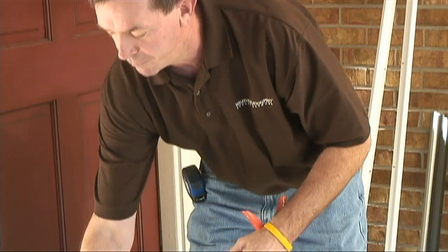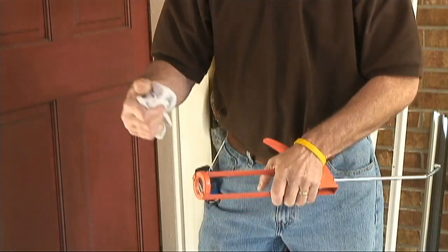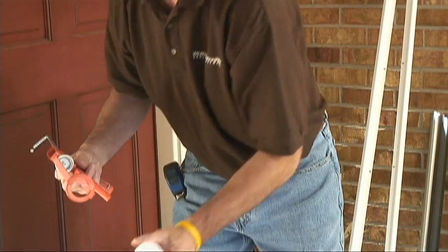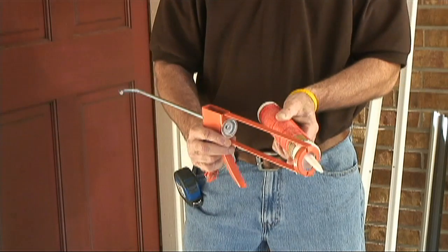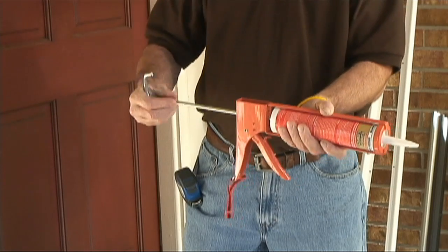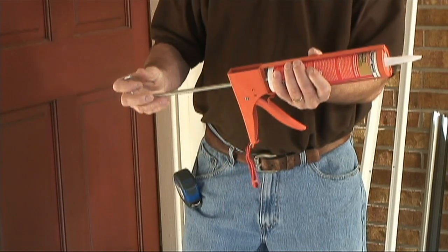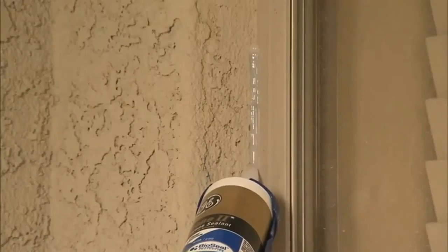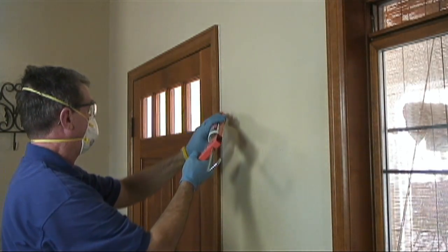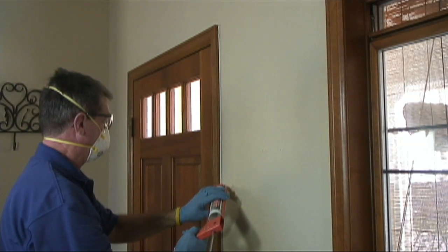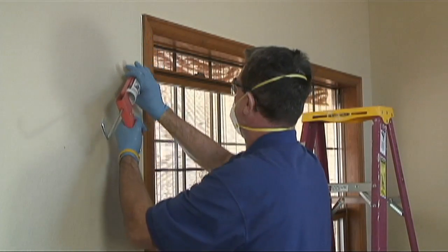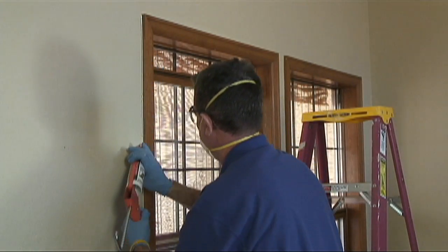Using the flip pin or a nail, break the seal through the nozzle of your caulk cartridge. Using the shaft and trigger of your caulk gun, apply pressure with your gun so that the caulk will flow from the tip of the cartridge. Install or apply a 1/8 inch bead of caulk into the gaps of the trim around the window, door, or area in which you are working. Run the bead out about 4 feet or the full length of a particular trim piece.